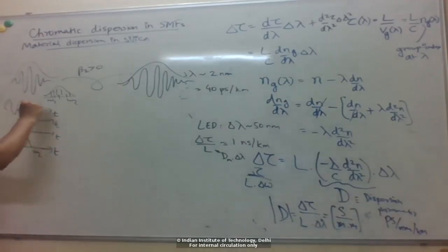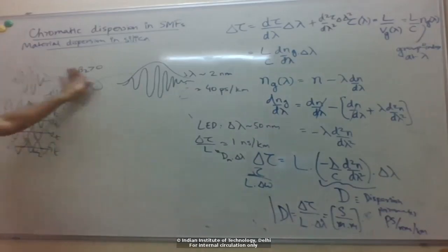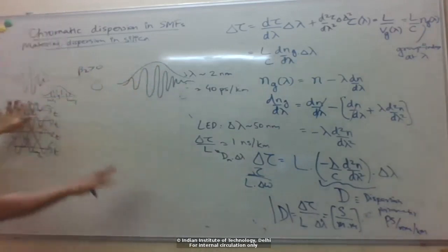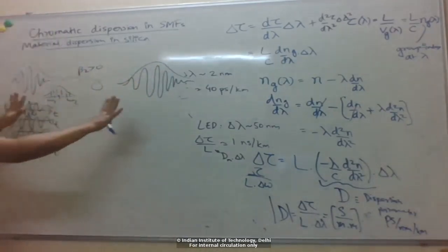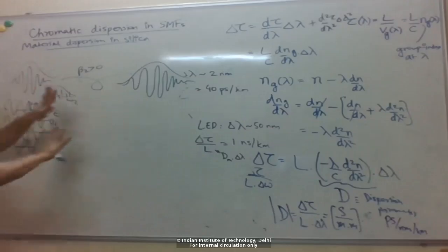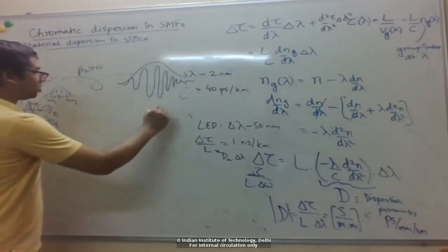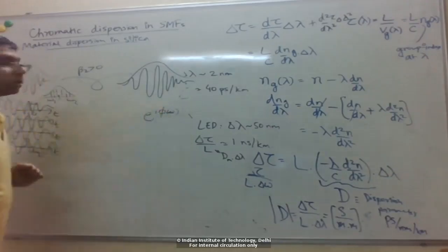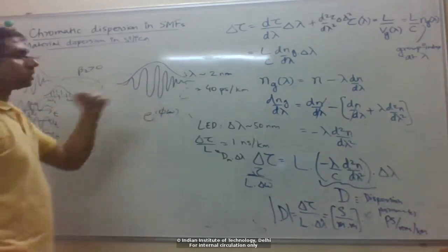Actually, these would be sine waves, because they are monochromatic. So how we get this pulse is by adding all these sine waves of different frequencies without any phase shift. They're all together. So that's an unchirped pulse. And now what happens when they travel through the fiber is, because they travel at different speeds, they have a lag with respect to each other, or a phase difference, right? That's what this frequency dependent phase I was talking about, which leads to this broadening.